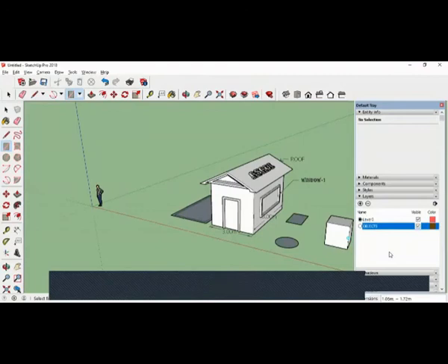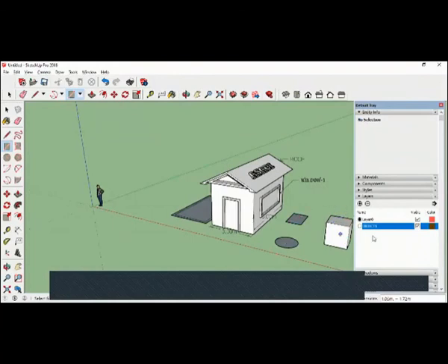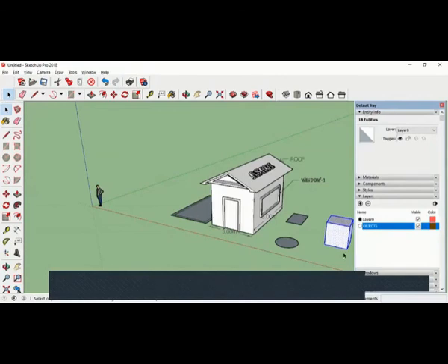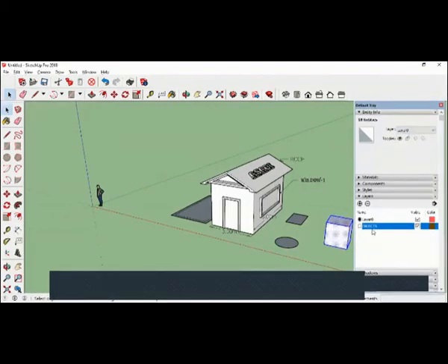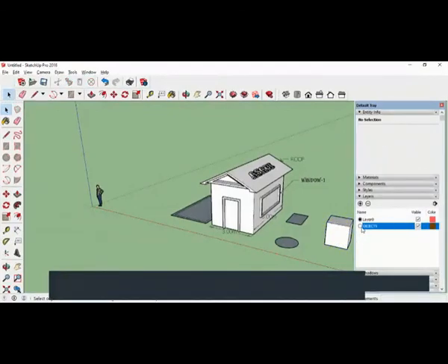So this layer is a very, very powerful command. Suppose you want to bring this box to this layer. Now, this box is in 0 layer. I want to change it to the objects layer. So what I will do, I will triple click and select it. Immediately you get the info, or right click and go to info. And you can see that the layer is 0. The object is in the 0 layer. So you select the objects layer, you use the arrow, objects layer. So now this box is in the objects layer. Okay, so if I make it invisible, the box also became invisible. So like that, you can change the layer from one layer to another.